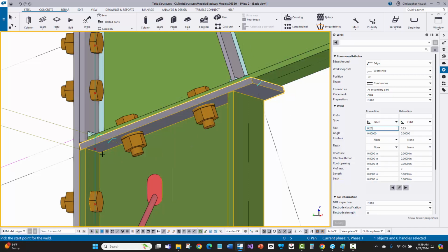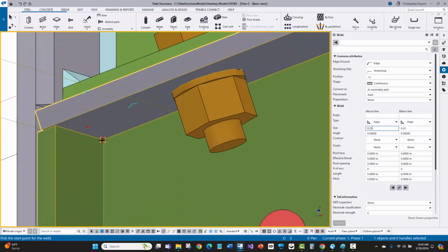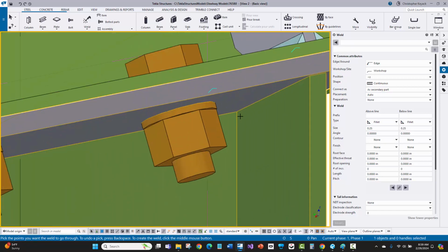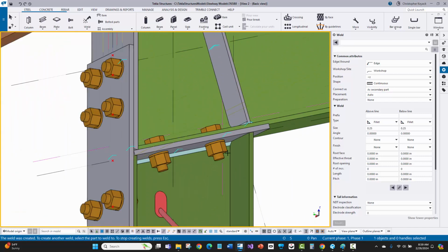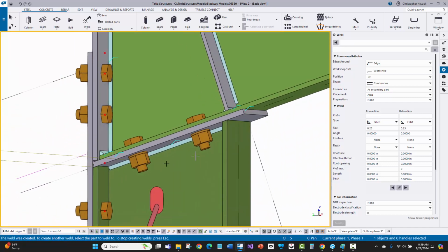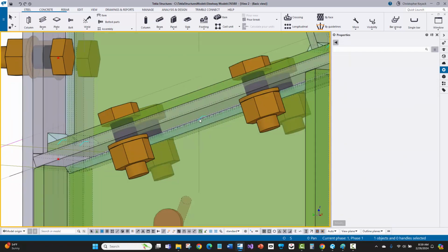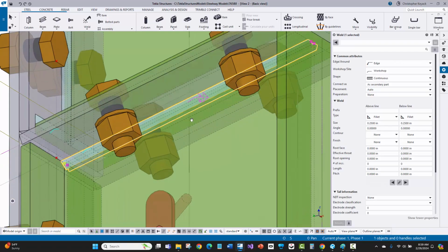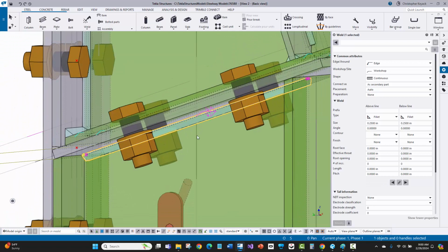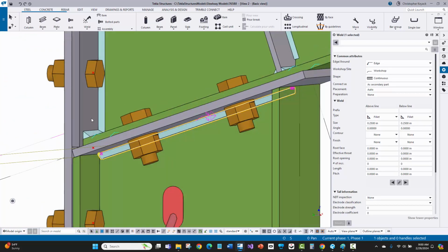Okay, so I'm going to get that near side, far side. I will come in here and click right at that corner and then click up here at that corner, middle mouse button. And there is that near side, far side weld created. Now, just to make sure, I might interrupt there and press Control-2. I just want to make sure that both the welds are actually drawn and shown. And it looks like they are, so that looks good. So then I'll just say okay there.